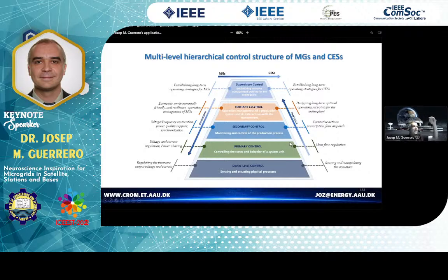And then the tertiary control, it can work like an energy management system, which in our brain is our prefrontal cortex, the one who's able to go into the future, make predictions, come back to the present moment, take decisions, a decision maker. So kind of an energy management system. Here we have something similar. It's an optimizer for long-term optimal setting points of the whole closed ecosystem. And then at the top of this, we put a SCADA system, a supervisory control, and in the bottom we put the control for each of the devices.